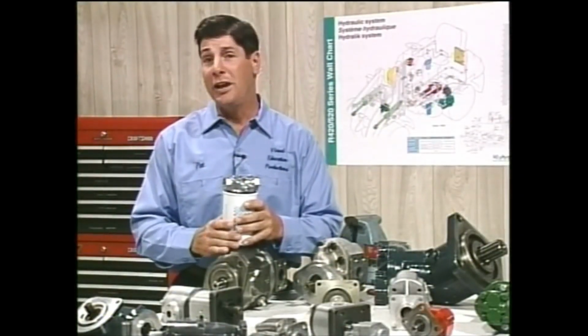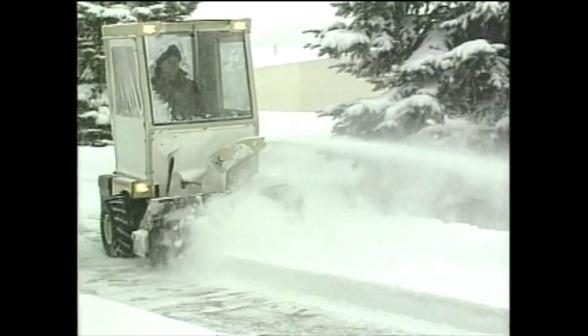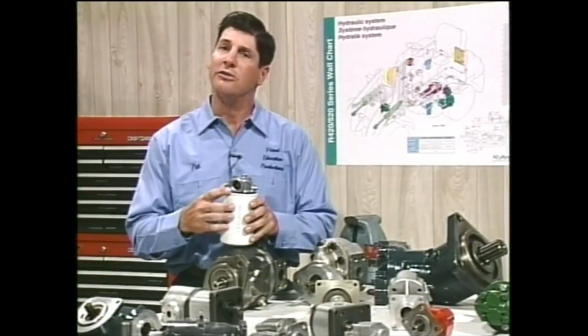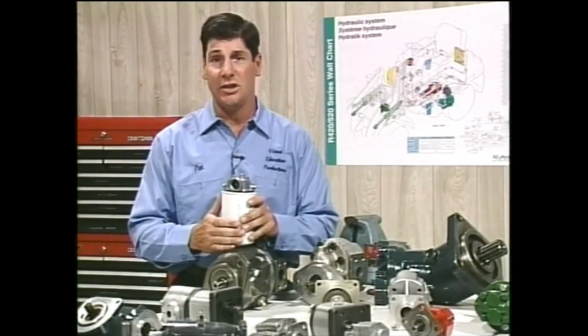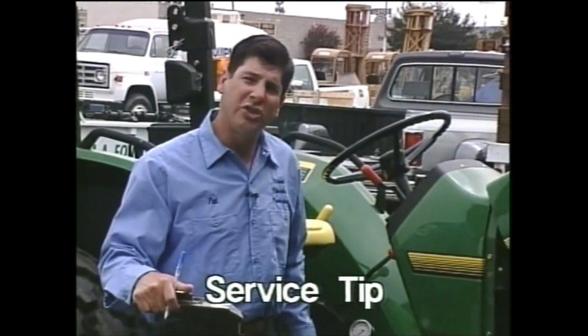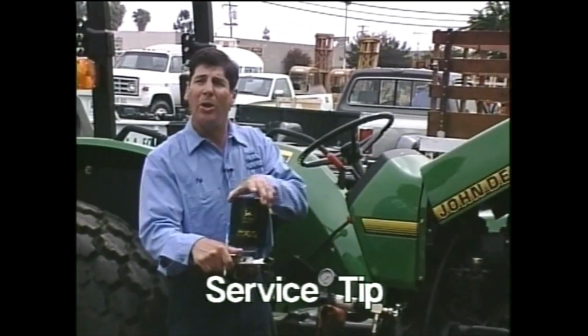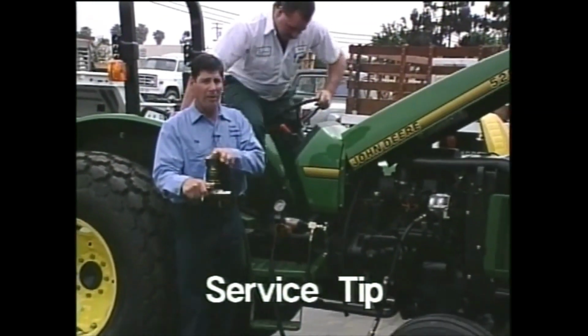Additionally, oil thickened by cold temperature may not easily pass through a partially plugged filter, and could cause the filter bypass valve on some equipment to open and release dirt and wear metal particles into the mainstream. It has been found from years of experience that many of the hydraulic pumps that are replaced during service are not at fault. Something else in the system is making the pump look defective. A restricted suction filter is a good example. Remember, if the pump can't get oil, it can't pump oil.